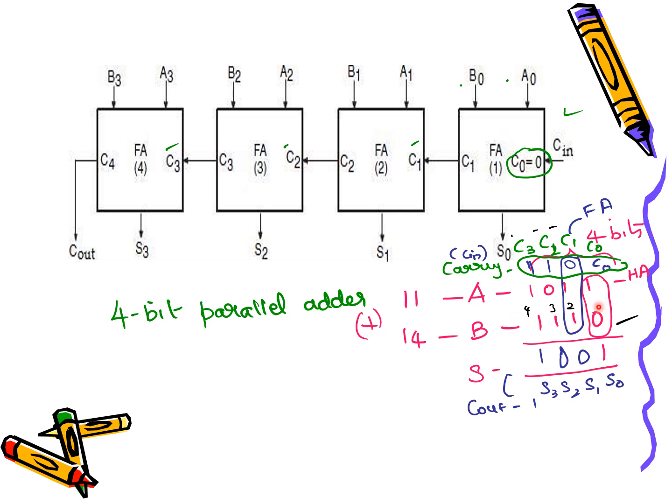So when you try to add these two combinations of inputs, for the first stage of addition, what is happening? You are adding 2 bits. To add any 2 bits, a half adder is enough. So 1 plus 0 is 1. So it is producing a sum, no carry is being generated. Okay. So the initial carry we call it C0. The next carry, if it's generated, we call it C1. So similarly for the others also.